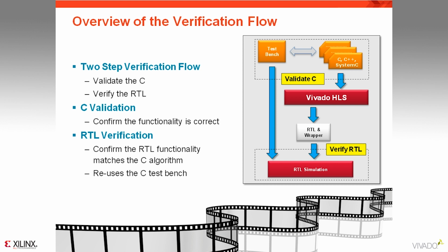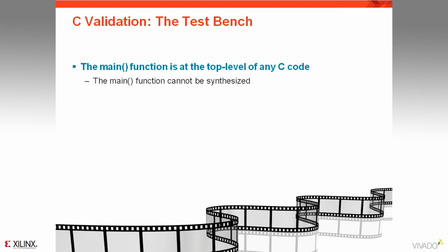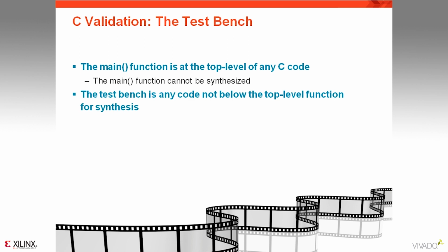Before we proceed, it's worth spending a few moments to discuss the importance of the C test bench and to explain what we mean by the C test bench. The main function is at the top level of any C code. The main function cannot be synthesized. Top level for synthesis is any sub-function below main. The test bench is any code not below the top level function for synthesis.